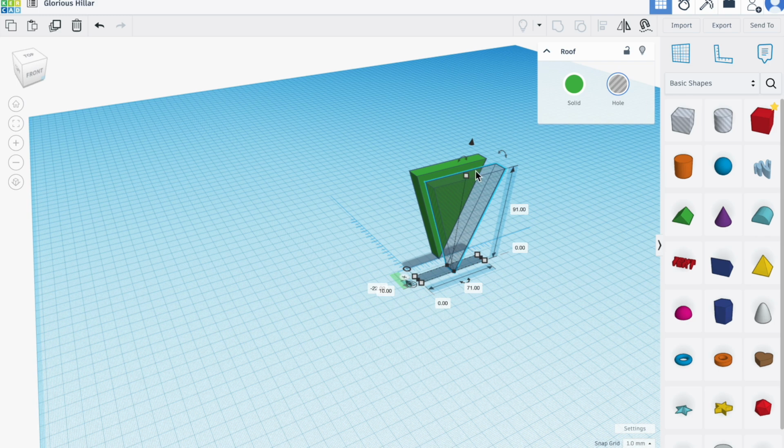If the popsicle stick is running face out along this edge, then you would simply deduct 9.5 from 91. So you'd have 81.5. So that would be your new height there. But then you also have to account for the fact that it's coming up a bit as well.